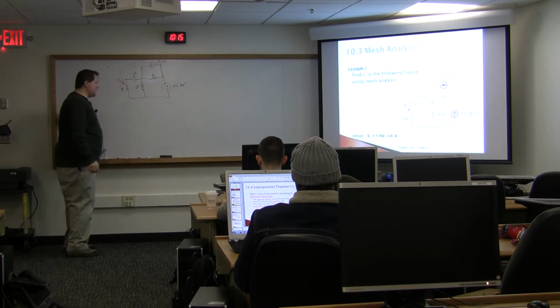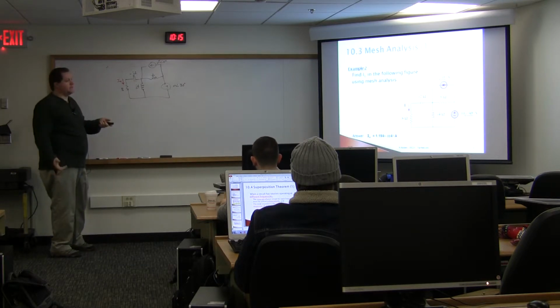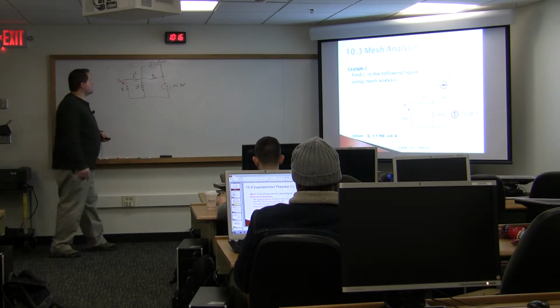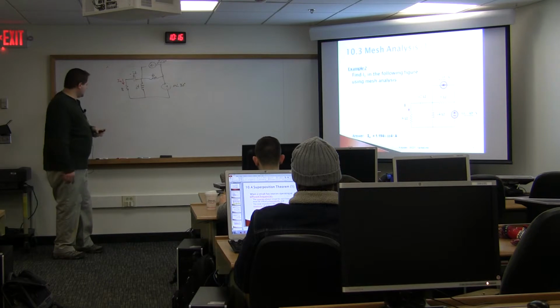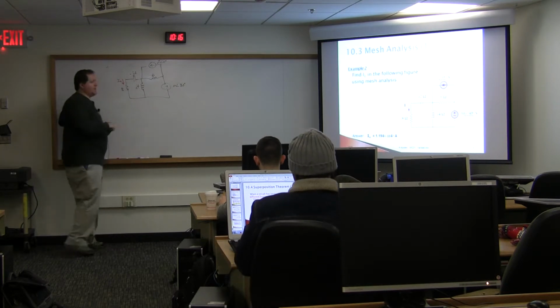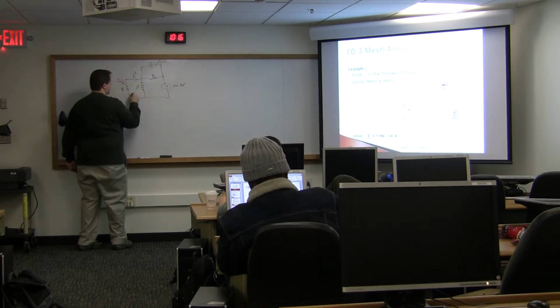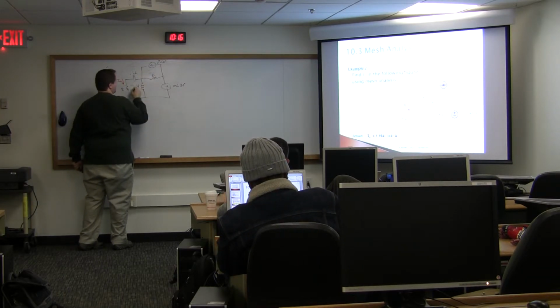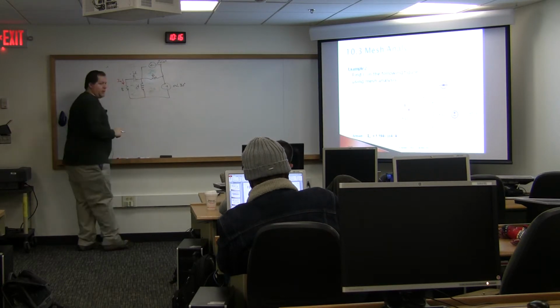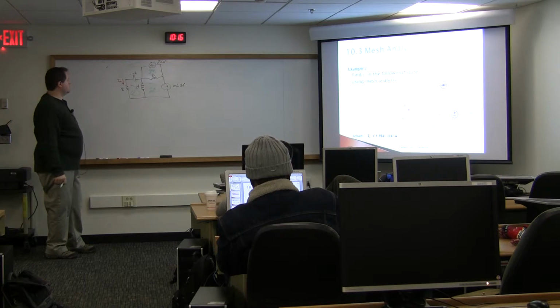And again, now that we've been given these, we can assume that they're cosines, but it doesn't really matter. What we do know is that relative to each other, the two different phasors in our circuit have a 30-degree phase difference, right? So I can apply mesh analysis. Mesh analysis says assign my little I1, I2, and I3, and I'm going to apply KVL around each of these loops.